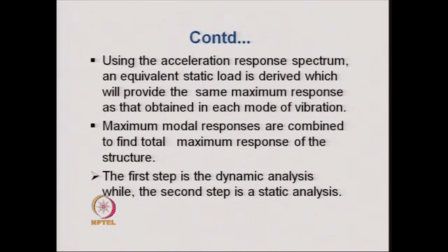Then, using the acceleration response spectrum, which is given in a code, an equivalent static load is derived which will provide the same maximum response as that obtained in each mode of vibration that I have explained earlier. The maximum modal responses are then combined to find the total maximum response of the structure.